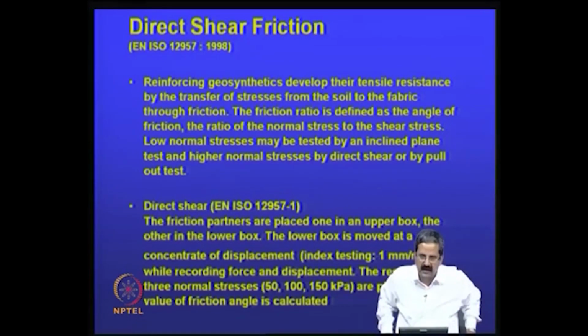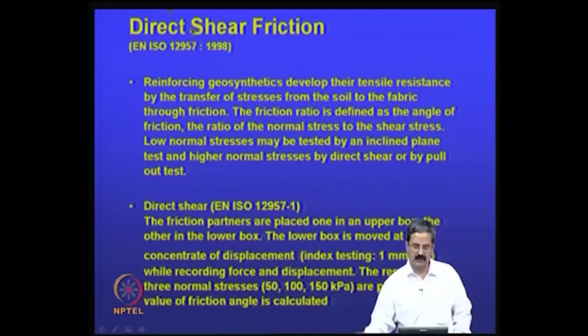If you want to see if a geogrid or a geotextile material is going to be good, you have to find out the friction, similar to the friction angle of the soil. We try to calculate the friction angle of the geosynthetic also, which we call the angle of interfacial shear resistance, similar to tan delta, which we use in soil mechanics. We normally have tan phi, but if there is a pile foundation, we use a factor called tan delta, which is nothing but 2/3 of tan phi.